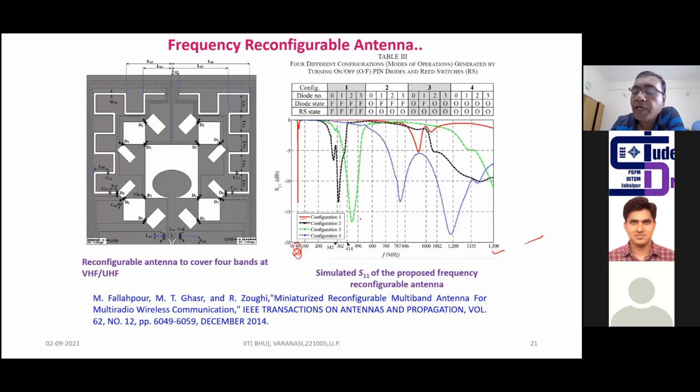Exactly, the on state and off state conditions we have to consider during the design. When you are considering the design part, you have to consider that L and C effect. It will be a part of your impedance; we have to incorporate it, you cannot neglect it. The lines also have inductance and capacitance because of the couplings, so we choose the width of the line so that you can nullify it. The PIN diodes have inbuilt, fixed C and L, and you have to incorporate those during your design. So no need to overcome or work on this additionally; it would be part of that.